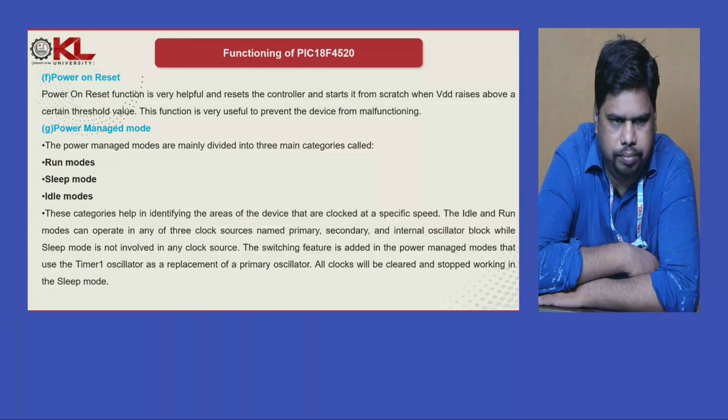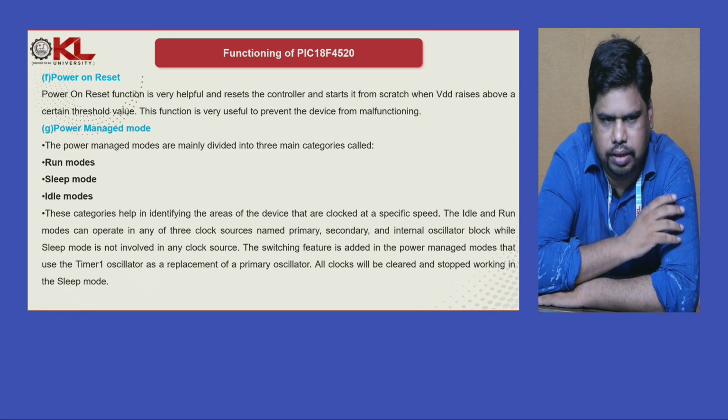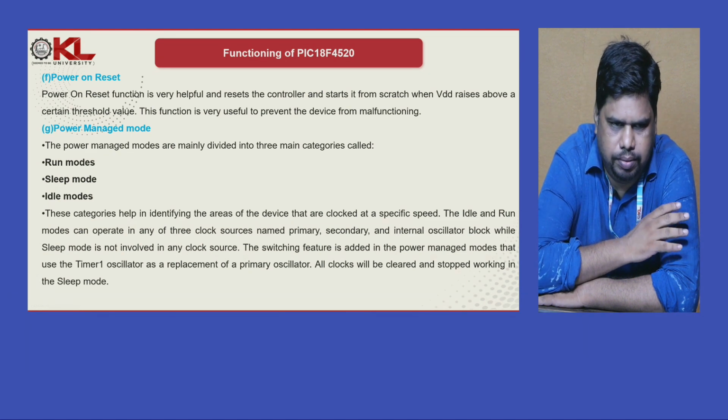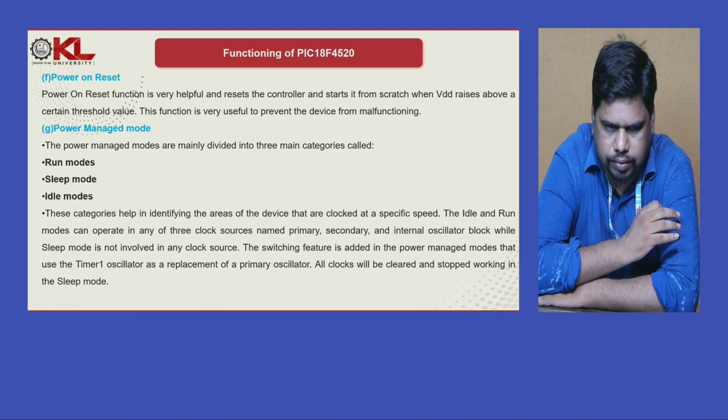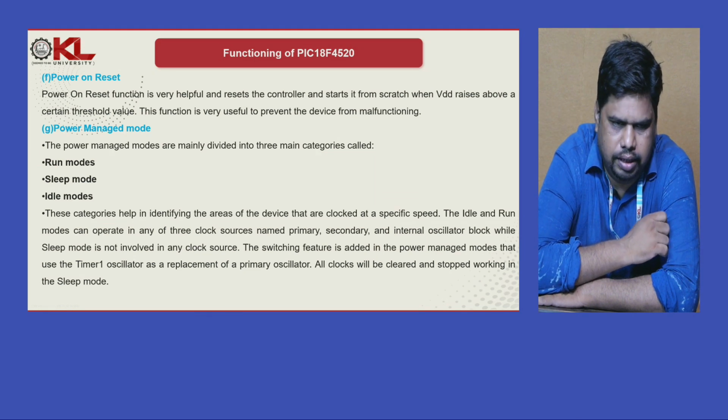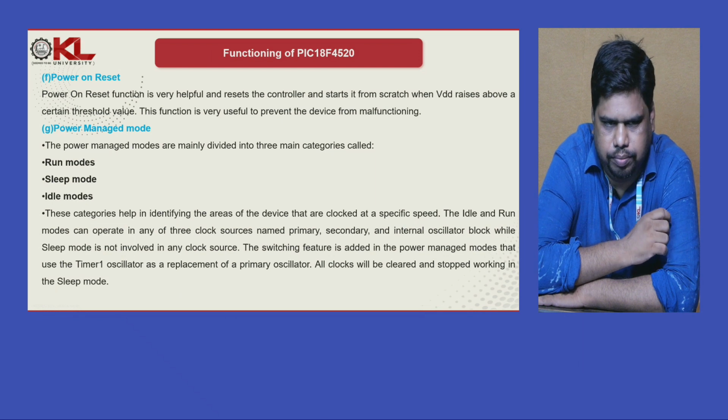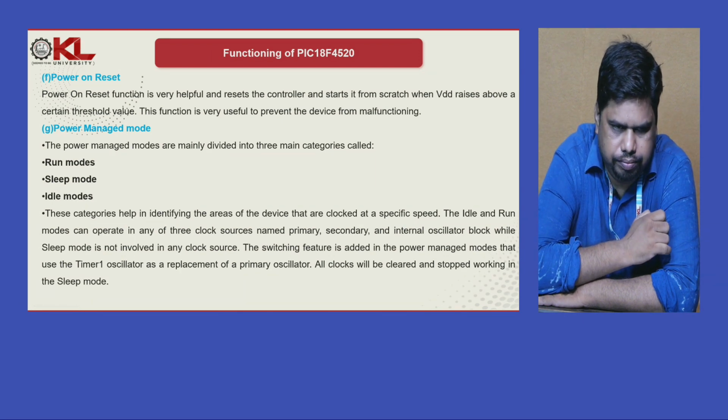Now we'll come to the power managed mode that is also available with this PIC. The power managed modes are mainly divided into 3 main categories, which define how it will manage the power: run mode, sleep mode, and idle mode. In run mode, the power supply is available and programmed here. In sleep mode, it will save power.